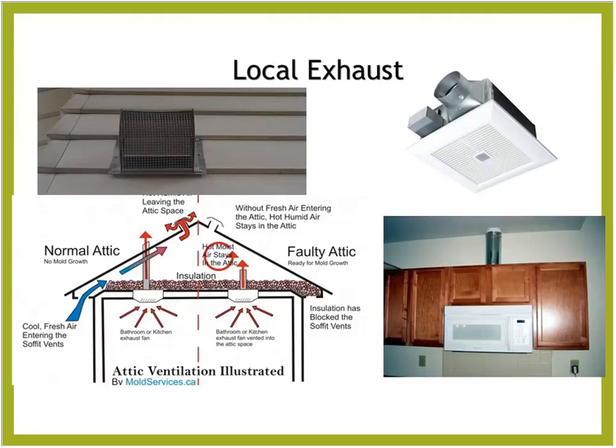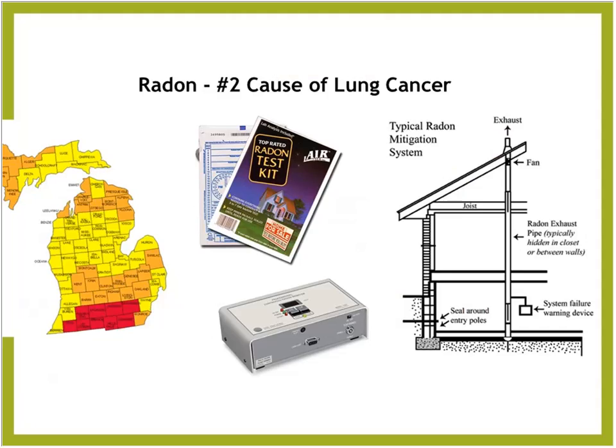The other thing to note with these, especially on the bath fans, is to get them tested by a rater and HVAC contractor to make sure that they're actually properly exhausting at the rate you've specified them to, because many times they're not. So it's important to look at that.